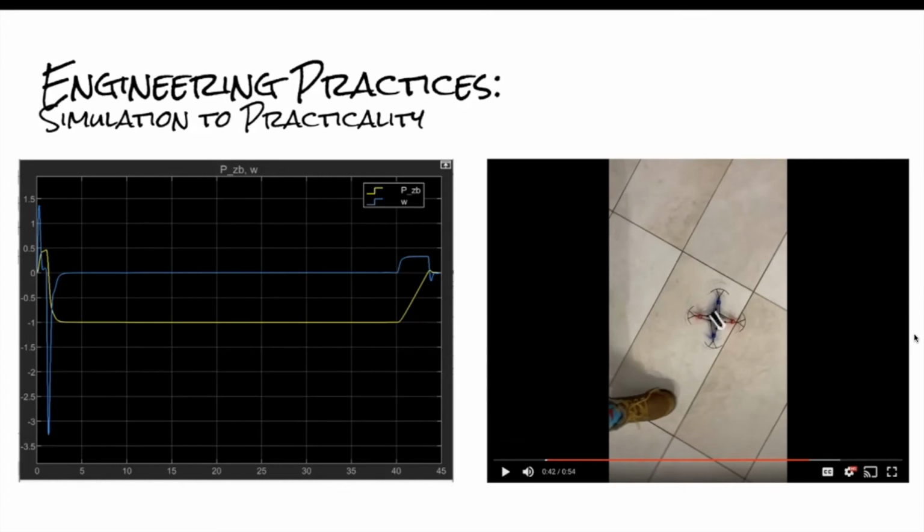So obviously, there are a lot of issues that we weren't necessarily expecting, like, for example, the drone not being able to get off the ground, continuously yawing. So it's really important to keep in mind the things that simulation fails to take into account. One big one that we ran into was time delays. That's something that in simulation you can make pretty perfect or assume to be pretty perfect, whereas in reality, things may be time delayed differently.